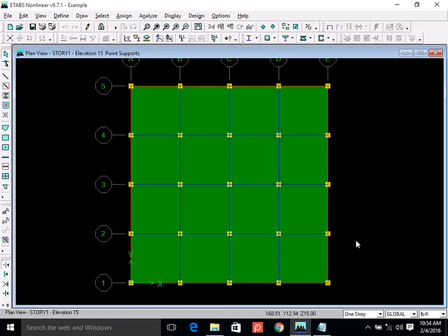That's 60 times 2.204, a little more than 120, around 132. So if in a classroom, in every 1 foot by 1 foot, one student is standing, then the load in this room on average can be 130 pounds per square foot.